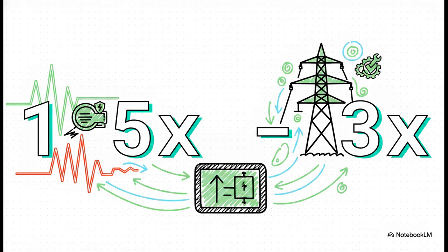Dedicated soft starters use components called silicon-controlled rectifiers. These guys gradually electronically ramp up the voltage. This allows them to take that terrifying 6 to 8 times starting current and dramatically drop it down to a highly manageable, incredibly safe 1.5 to 3 times the full load current. It's a real game changer that protects the machine and the grid simultaneously.